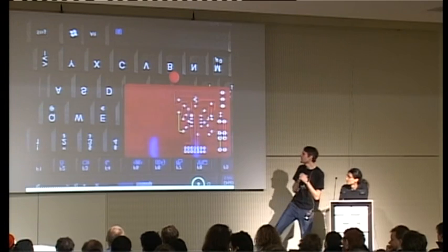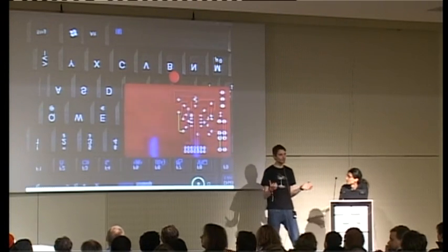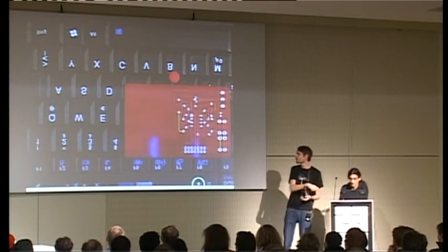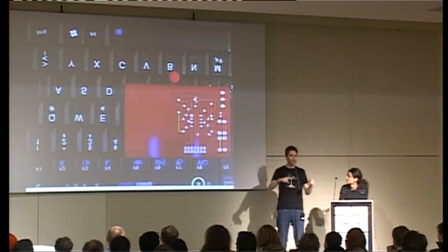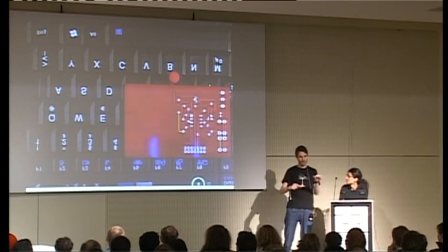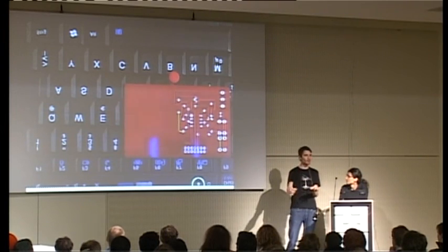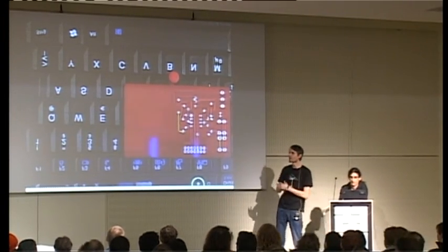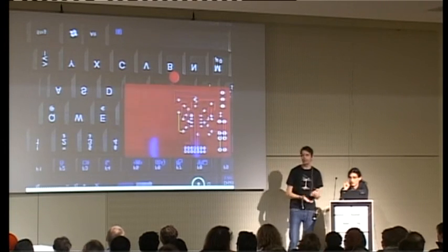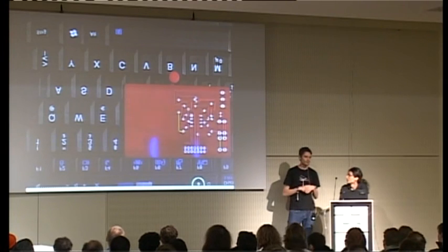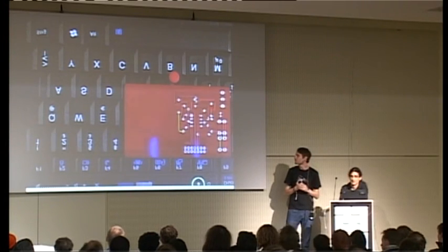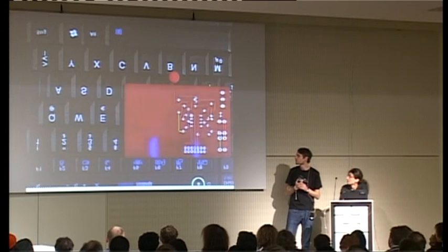What I want to do instead is use a web camera and a multimeter over the top of a PCB, just like Vadik had. As you move the probe around, when it hears a beep, it knows, oh, this is the edges of the probe, so I place a dot here and a line to that dot there. So, let's call it assisted manual tracing, which is of course more useful when you have more than 2 layers and you can really see what's going on inside them, so you can trace them visually.